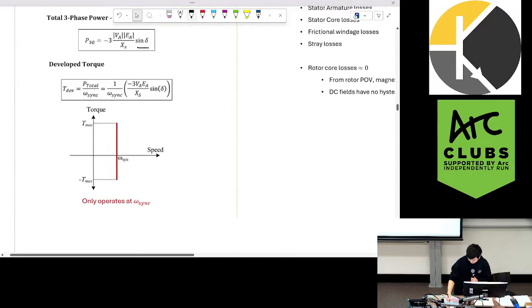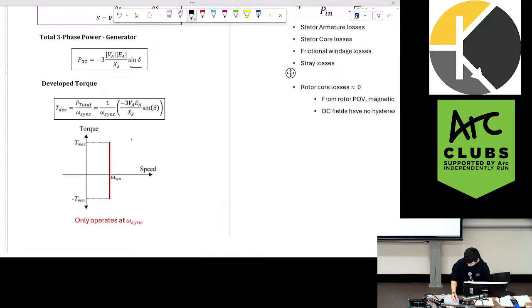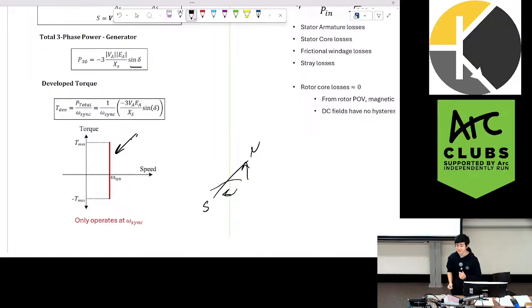Something to note is, yes, synchronous machines, they are synchronous. And so the torque speed characteristic is just along the straight line of the speed. If we were to have any slipping, like actual speed slipping, jumps out of an electrical degree, electrical rotation, it would mean that my north-south are over here, I'm lagging behind, and then suddenly I'm being pulled towards the opposite direction as opposed to where I was initially going.